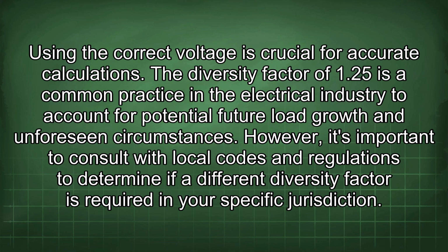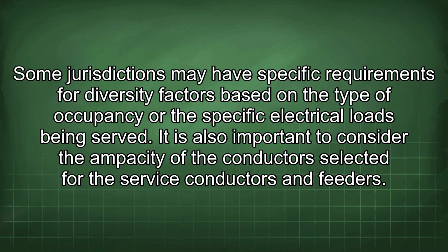The diversity factor of 1.25 is a common practice in the electrical industry to account for potential future load growth and unforeseen circumstances. However, it's important to consult with local codes and regulations to determine if a different diversity factor is required in your specific jurisdiction. Some jurisdictions may have specific requirements for diversity factors based on the type of occupancy or the specific electrical loads being served. It is also important to consider the ampacity of the conductors selected for the service conductors and feeders.